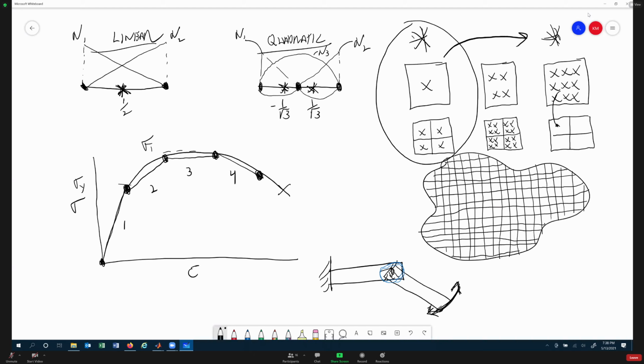So you would either have to manipulate the input coming in, knowing how this finite element mathematics works, to get a different output. But I'm pretty sure all of them will allow you to design your own element as an input. So you can actually create an element with your own shape functions. You could define your own element type, which is a shape function, integration rule, the whole deal. You can customize and build your own element, and that's an input into this black box. They usually call it the solver. So that could be a parameter that you're pumping into the solver, and then you get an output.